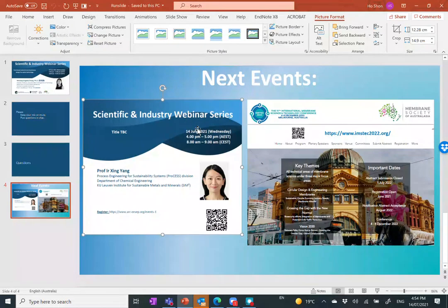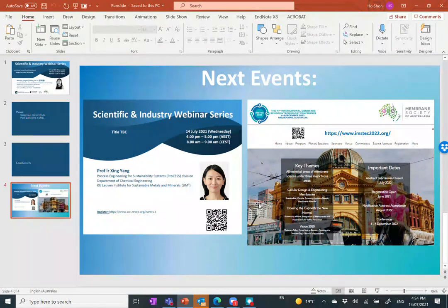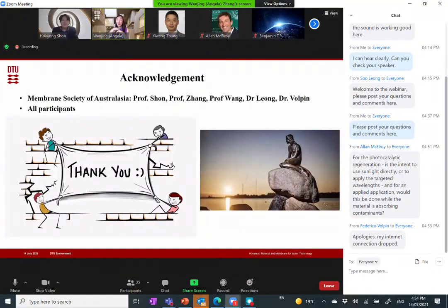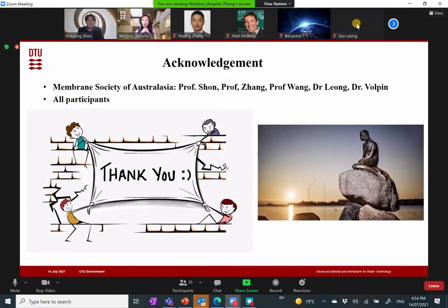If we can have such membrane filtrations and can introduce the lights. For instance, I saw some of them introduce light with LED lights and just put it inside of the filtration unit. And that's a way to induce the photocatalytic degradation in situ. In that case, you don't need to take it offline or do it in some other place. But the principle is that once you have the light source, you will be able to generate these radicals for the degradation. Okay, Alan, is it clear for you?